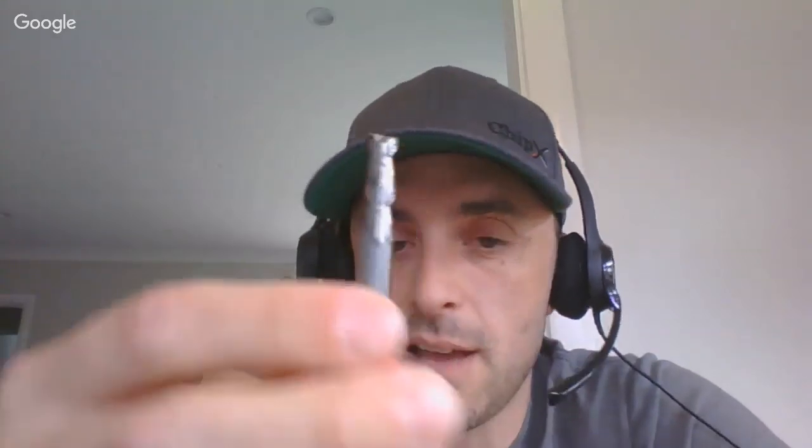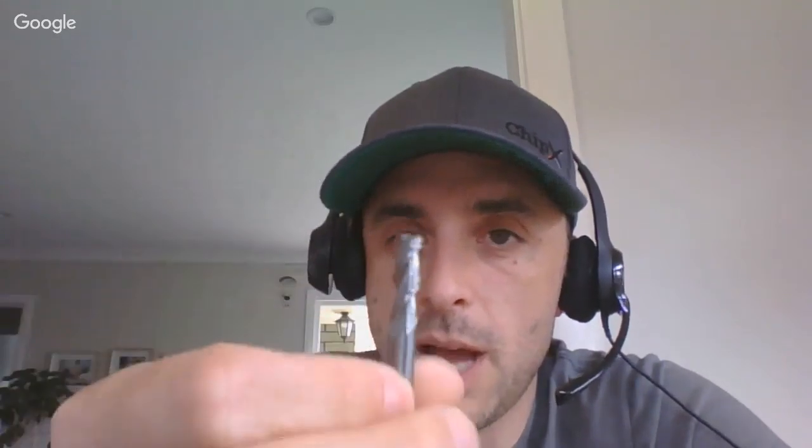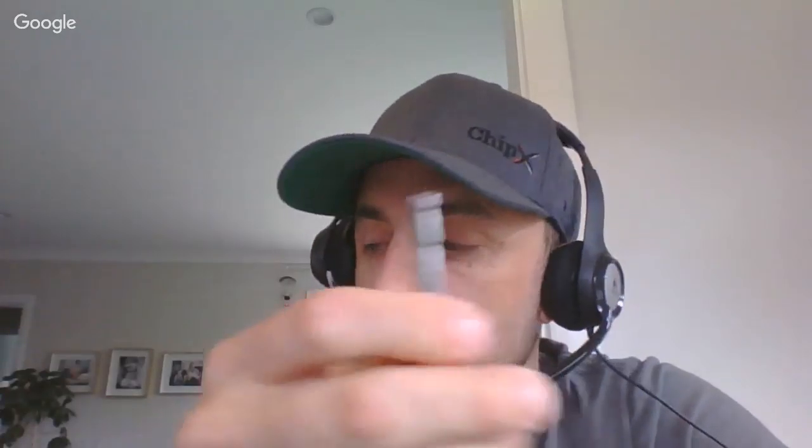I tend to find on 6mm cutters, I don't know what the exact RPM is on the Makita router that I'm using, because it doesn't have an RPM output, but I'd imagine I'm probably in the 5 to 10,000 RPM range most of the time with a 6mm cutter. If I'm going down to some fine engraving with a sharp point, I can't spin that thing fast enough, because the surface speeds become so low when you're doing shallow engraving.